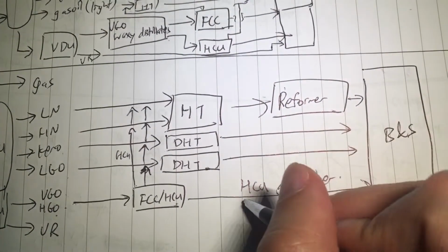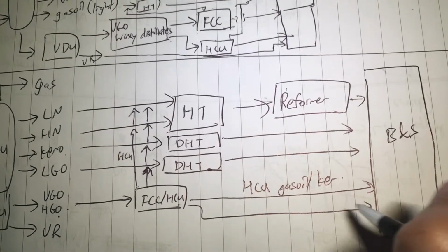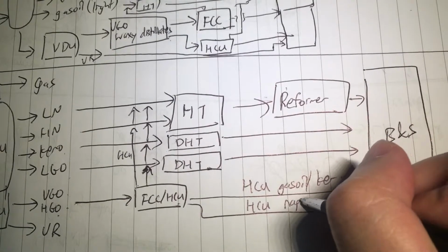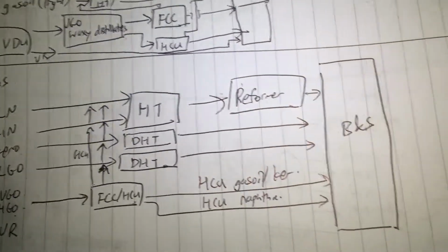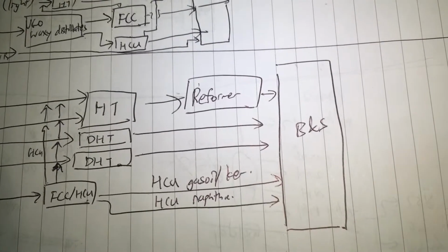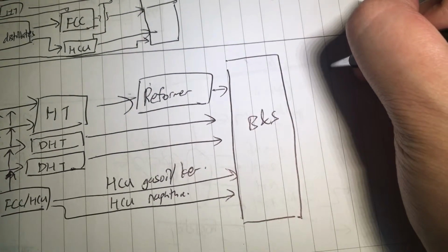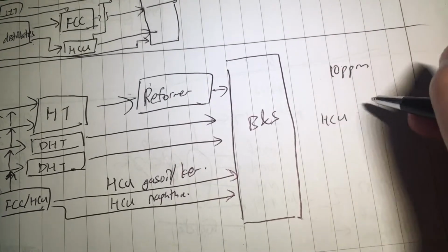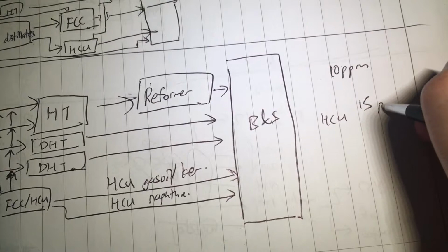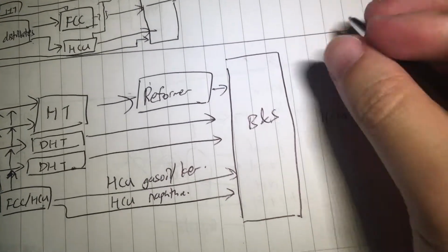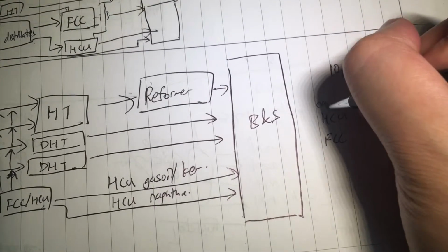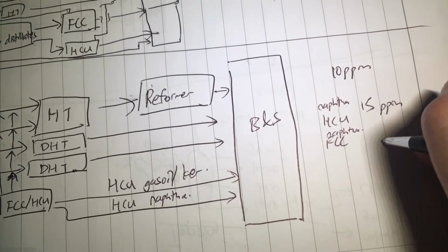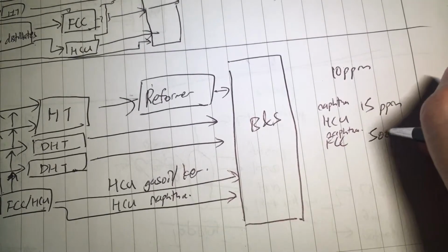Oh, and the alternative is to send some of the naphtha from the hydrocracking unit into blending and storage. Because if, let's say the sulfur spec is 10 ppm, and my hydrocracking naphtha is about 15 ppm, I'm just pulling numbers out. FCC naphtha maybe it has something like 500 ppm.